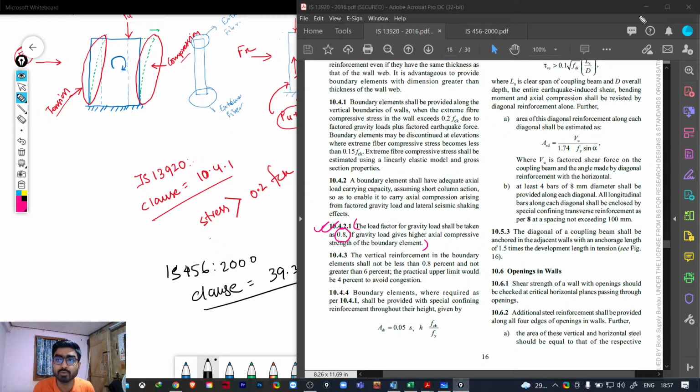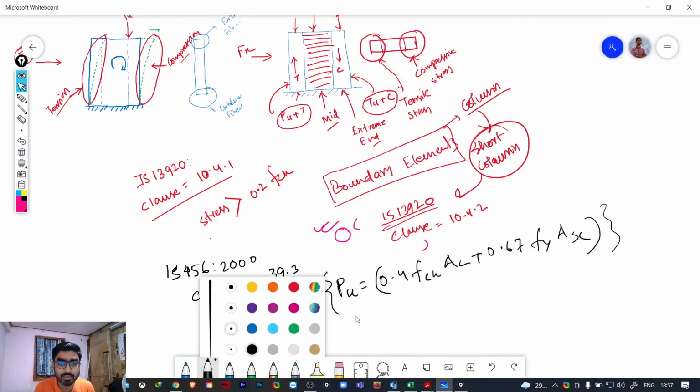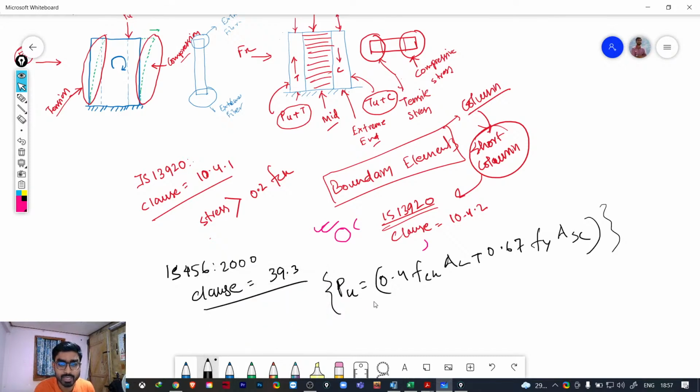So the best process is, for the shear wall, you can just multiply 0.8 with the total formula. So we are not considering 100%, we'll be considering this 0.8 factor. That means maybe you can say 80%. Okay, but I won't say 80%, it is 0.8 times, not one time. One time means we are considering 100% of the effect.